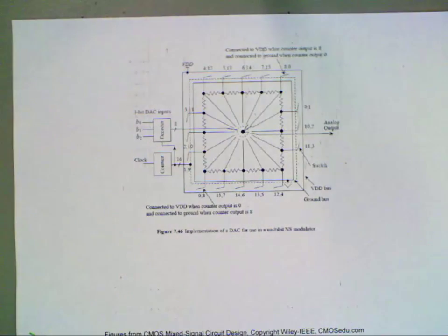Okay, any questions on, so the takeaway, if somebody says, what's the drawback of using multi-bit converters? Linearity in the DAC, because it's not a one-bit DAC. How do you get around that? People use dynamic element matching using randomization of the unit elements in the DAC. Any questions?